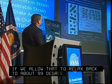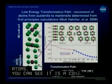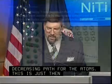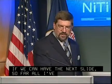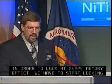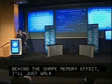On the bottom is the energy for that particular movement of atoms, and as you can see, it's a continuously decreasing barrierless path for the atoms, and this is just then one of the views of how these atoms actually move. Now, if we could have the next slide. So far, all I've talked about is the effect of temperature on the phase transformation itself, but in order to look at the shape memory effect, we have to start looking at it in 3 dimensions. We have to add stress and strain to the equation. And so in order to understand the mechanism behind the shape memory effect, I'll just walk around this slide starting at point 1 and working clockwise around the figure.